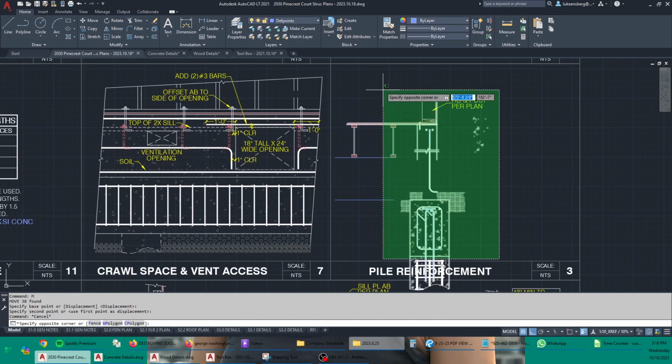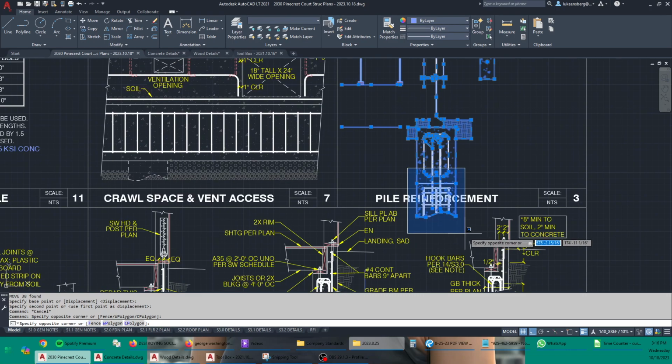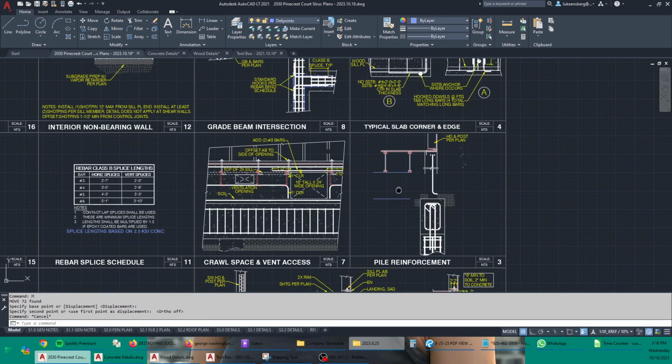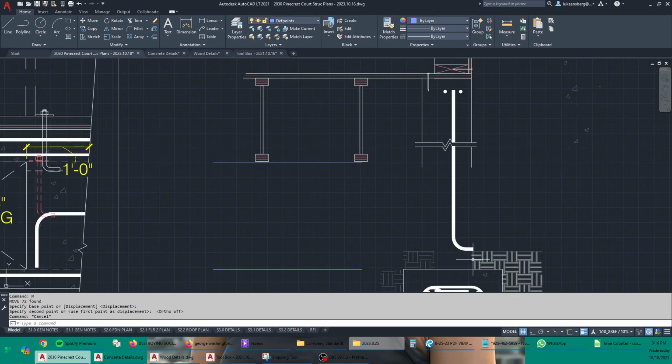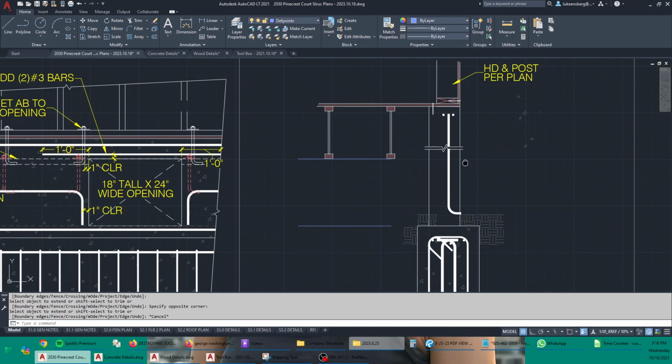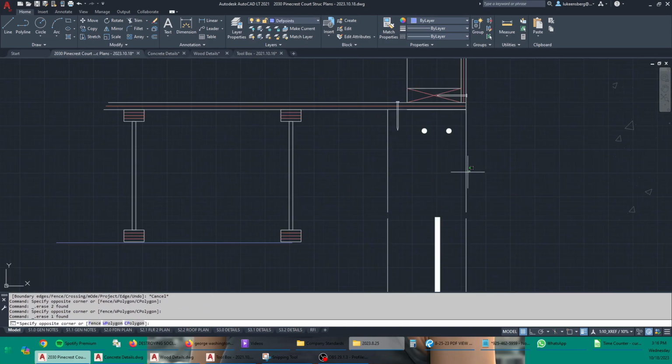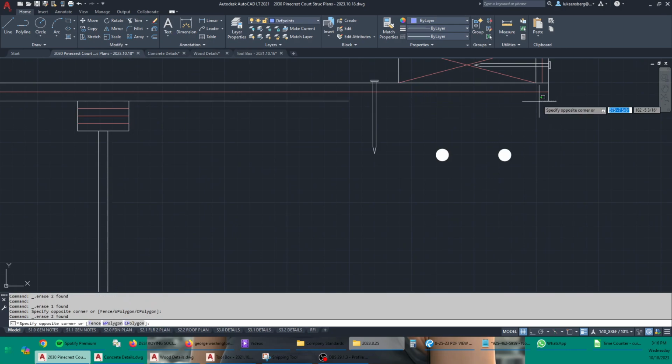All right, and then let's grab this stuff and bring it up like this. Okay. All right, and now let's bring our concrete wall edges down like that. This can go away because I've actually drawn this. I don't need break lines. I'm actually drawing the accurate length. Break lines are just a way to clue in somebody looking at your drawing to say, hey, I'm skipping something here.